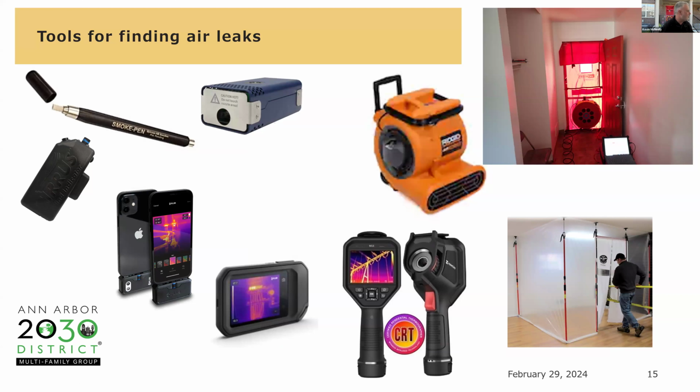Here are some of the tools that you can use for finding air leaks. So these top three right here are all smoke generators. The smoke pen is the least expensive, at about $40, but you do basically light it on fire. It smokes like a cigarette would. This one down to the left of the smoke pen is just a small smoke generator. That's about, I think, $80 or $90. It's under $100. This one to the right of the smoke pen will put out a lot of smoke. It is a handheld unit, but it is right around $900. You can do just fine with these two items here, finding leaks.